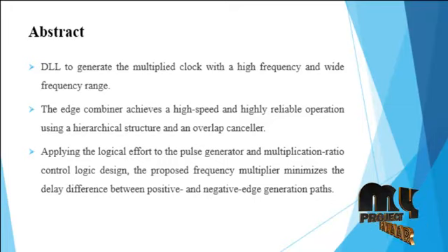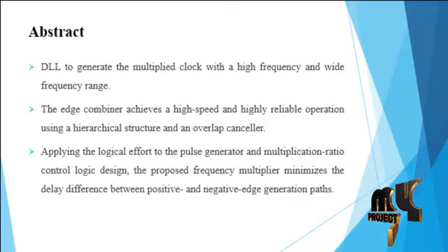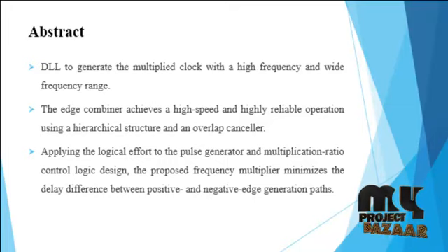The proposed edge combiner achieves high speed and highly reliable operation using a hierarchical structure and an overlap canceller. Finally, a numerical analysis is performed to analyze and compare the performance of the proposed frequency multiplier with that of previous frequency multipliers. These frequency multipliers achieve low power consumption by applying a relaxation oscillator block.